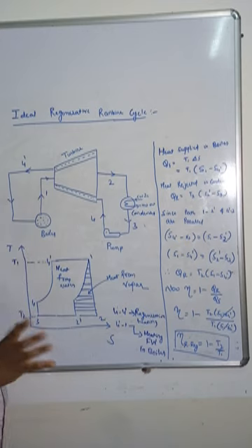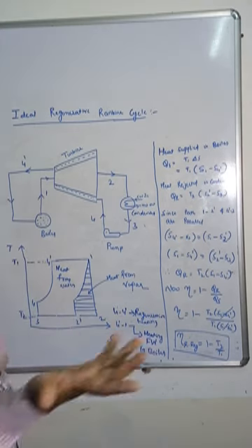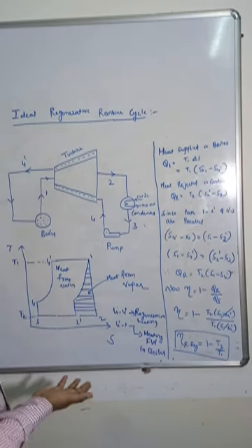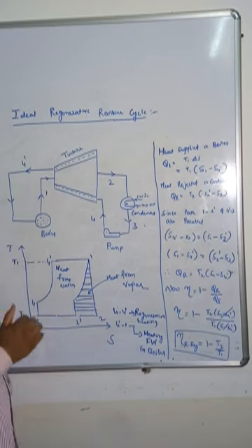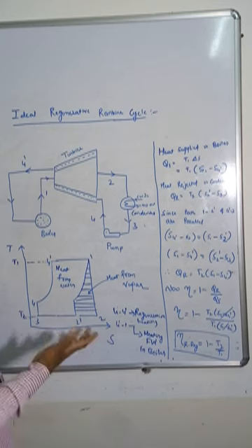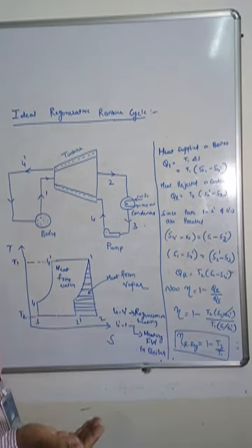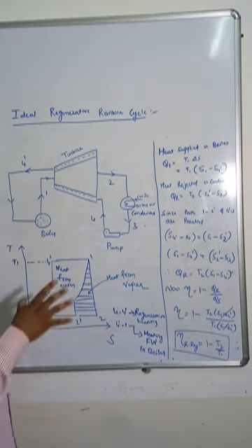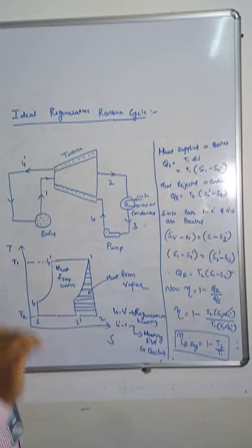Whatever input goes to the boiler is normal water, right? If I send preheated water, that is, water at a somewhat increased temperature, the boiler fuel consumption will be reduced.